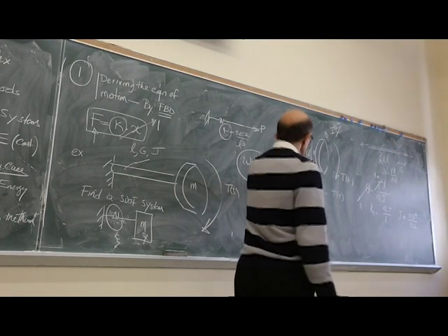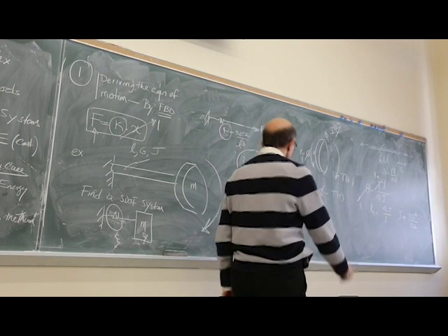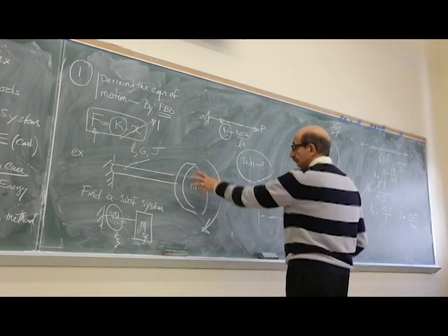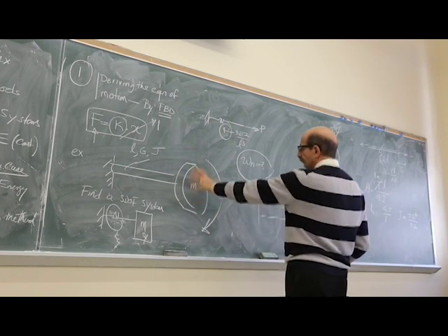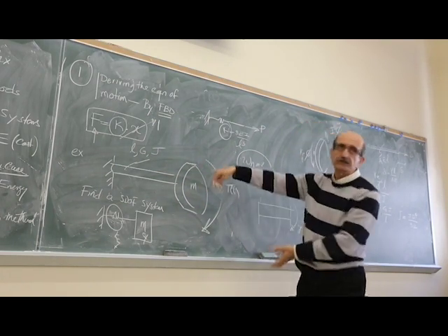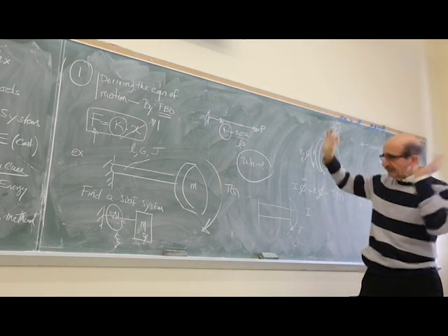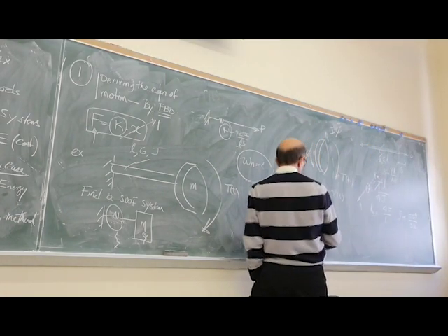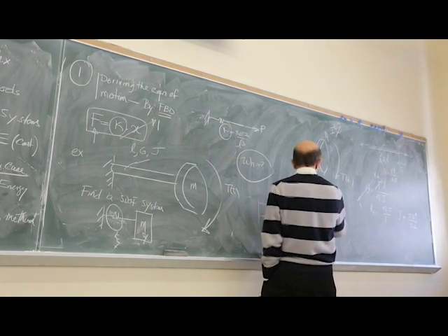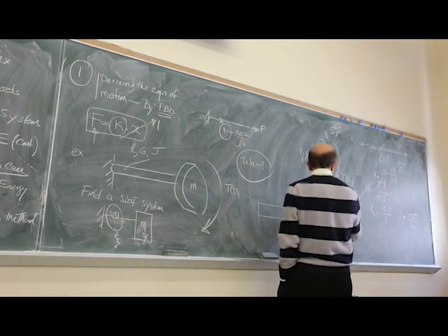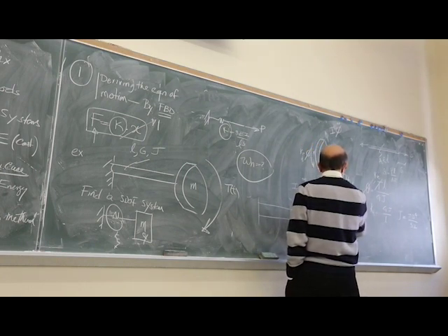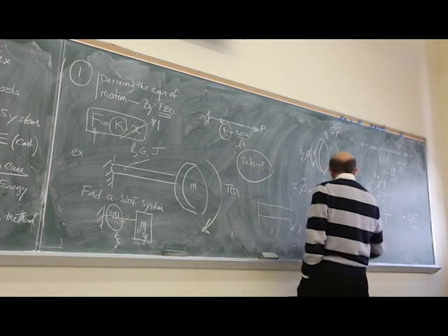Okay? So you just substitute for those in here. I is the mass moment of inertia for this lumped mass. If this was a disk at a radius r, it would be something else. Let's just assume that it's just a lumped mass. So it's I phi double dot plus, I will substitute for this, K T would be GJ over L, phi is equal to T.